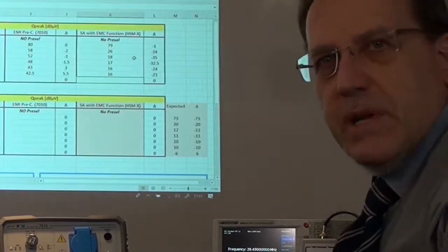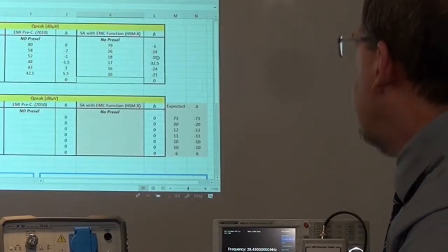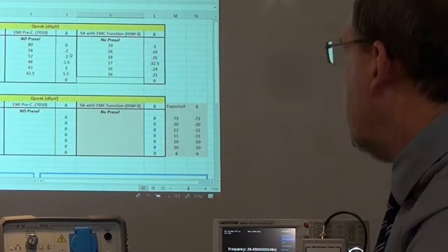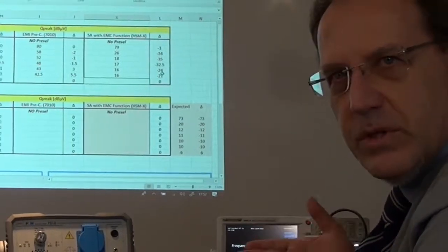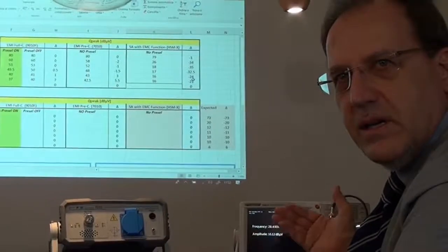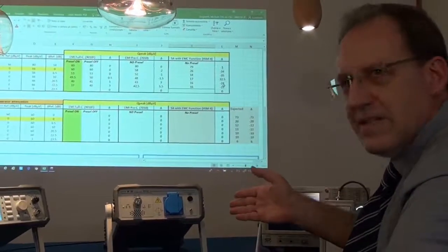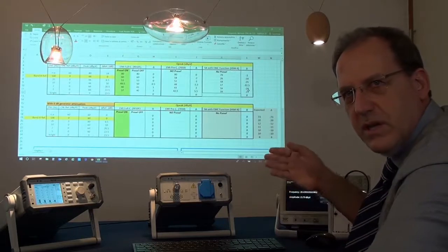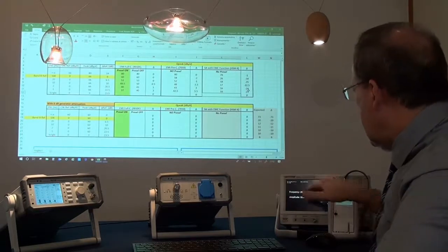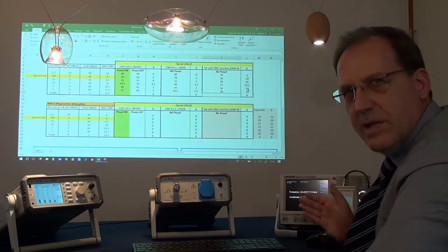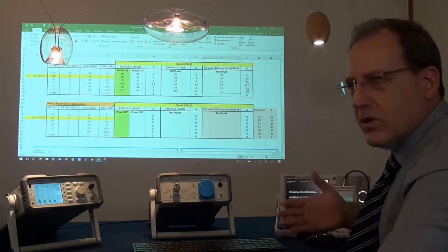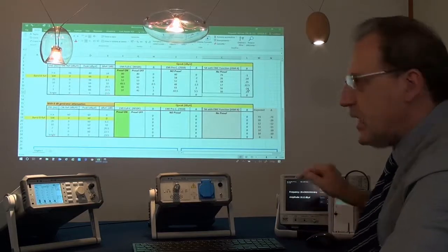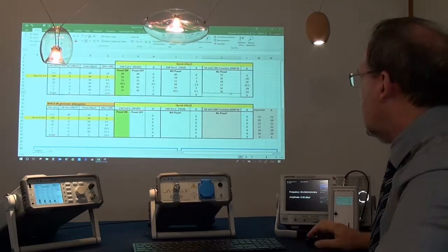You can see almost the same value. So here, what's happening? You can see the deviation is very, very high with respect to the other values that we have measured with the receiver. And this is exactly the demonstration of missing an attenuator that is possible to adjust frequency by frequency like in a receiver, because the receiver is tuning that frequency and is adjusting the attenuator based on that one, while the input of the spectrum analyzer is wideband and the attenuator is only one to adjust the whole contribution of the signal we are getting at the input.